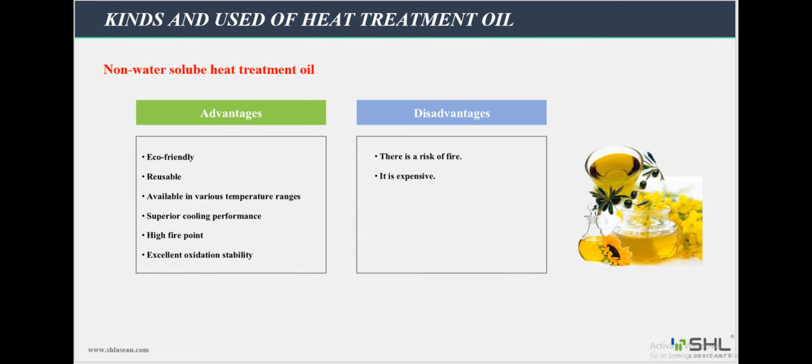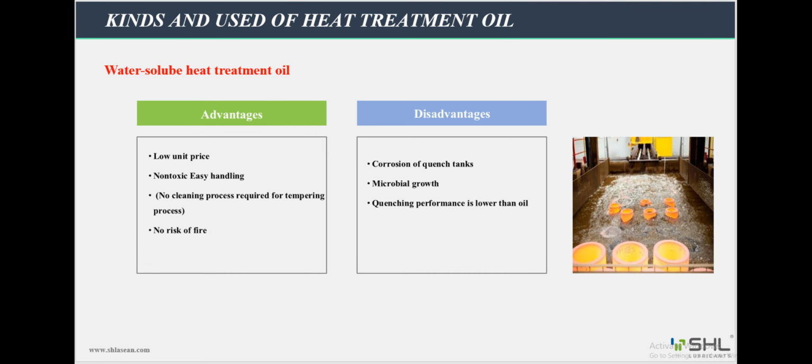With water-soluble oil, the advantages are low risk of fire, low cost as it is available, less environmental pollution, easy post-treatment, non-toxic, and easy handling. About disadvantages, water-soluble oil causes corrosion of quench tanks, causes microbial growth, and its cooling ability is lower than water-insoluble oil.